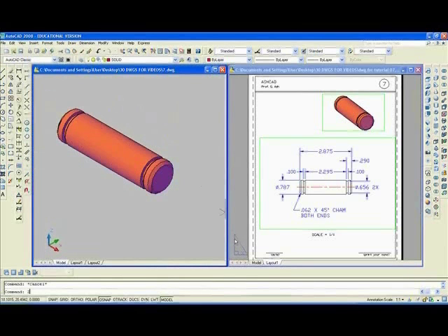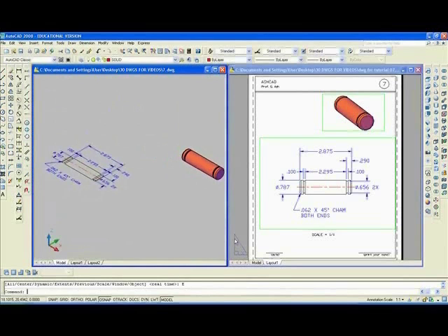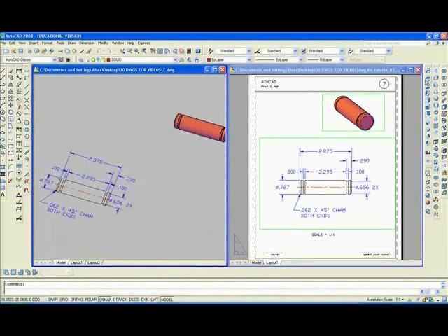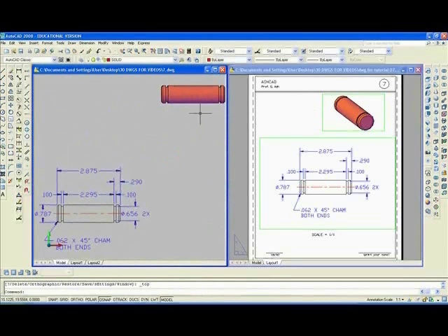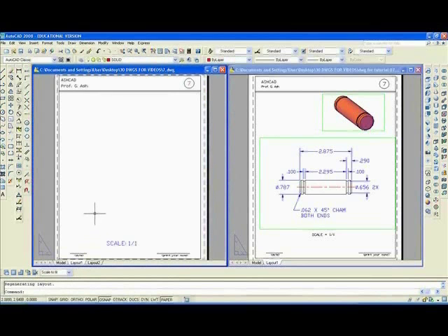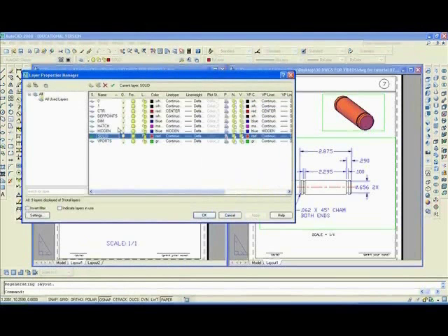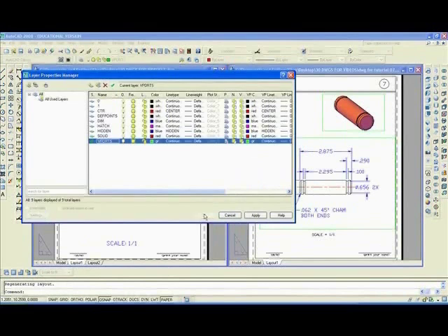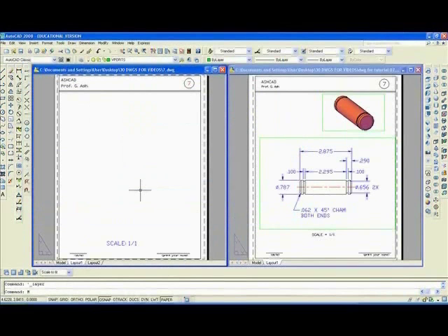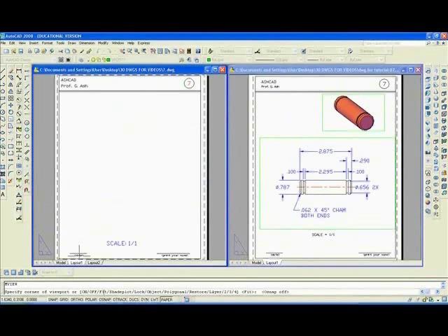So anyway, I'll zoom extents, Z enter, E enter, and then I'll move into the top view and I'll go into layout or paper space. Next, I'm going to have to change the viewport, make the viewports layer current. MV, enter. I like to take off the O snap when I do that.